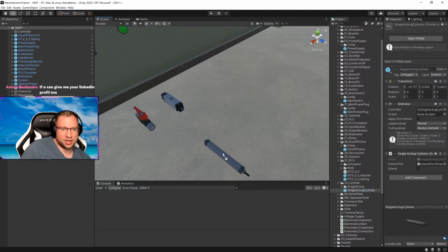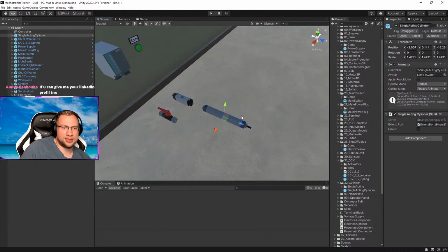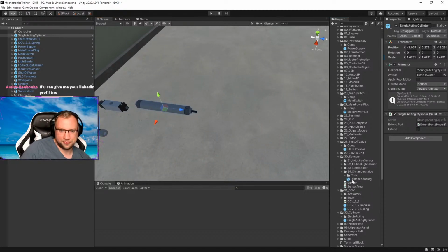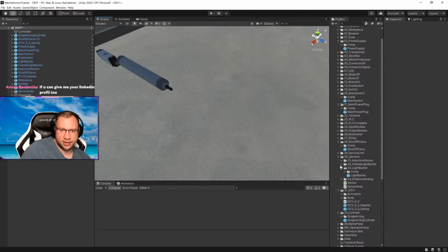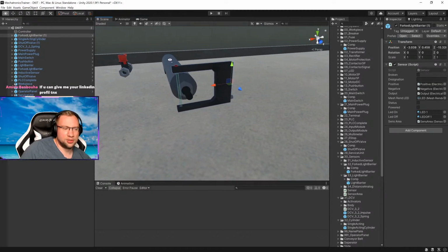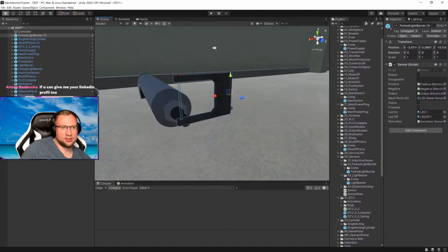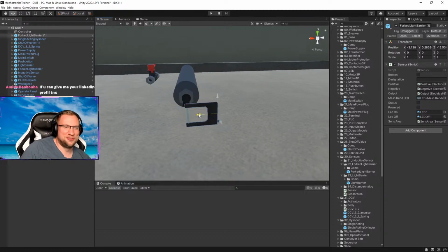Whoa, if all of this works, I'm really gonna be so flashed. Okay, so this is gonna activate this cylinder. This cylinder here is gonna be detected by the sensor. I could take the analog sensor, but I'm taking a light barrier. Oh, another light. A forked light barrier. Now I need to take care of the placement of the sensor, of course. So let's place it so that the thing will actually detect it. Oh god, do you know how much wiring I have to make?